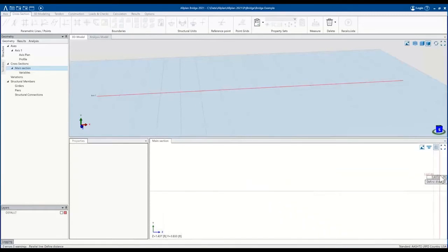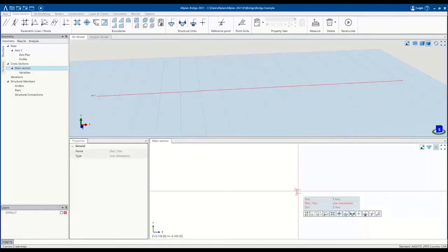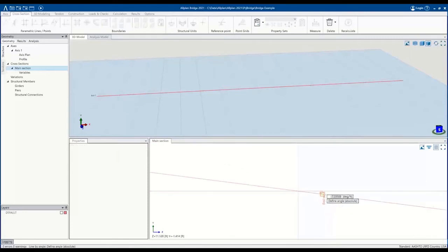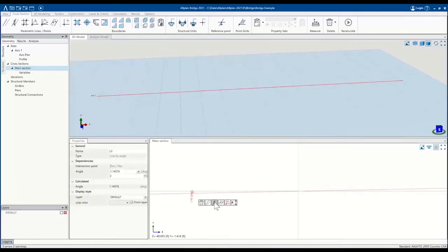And these are going to be parametrically defined to help us apply variations or different depths within a superstructure as needed. We'll put a cross-section slope of 2%. And then, whoops, there you go, -2%. And then we could go ahead and also add a deck depth.